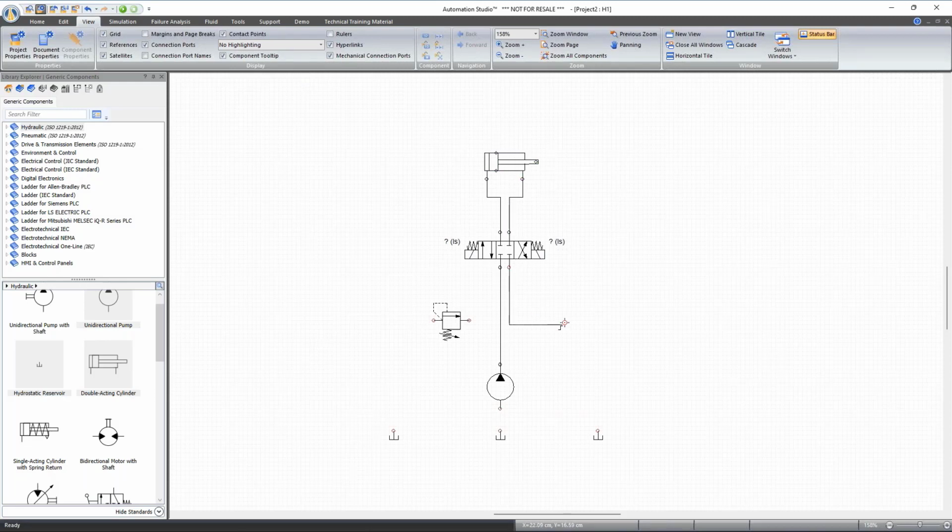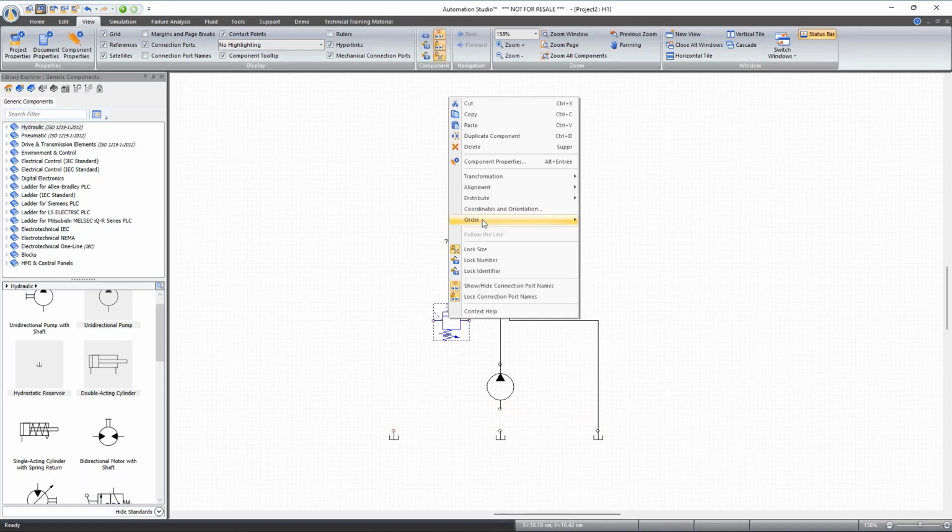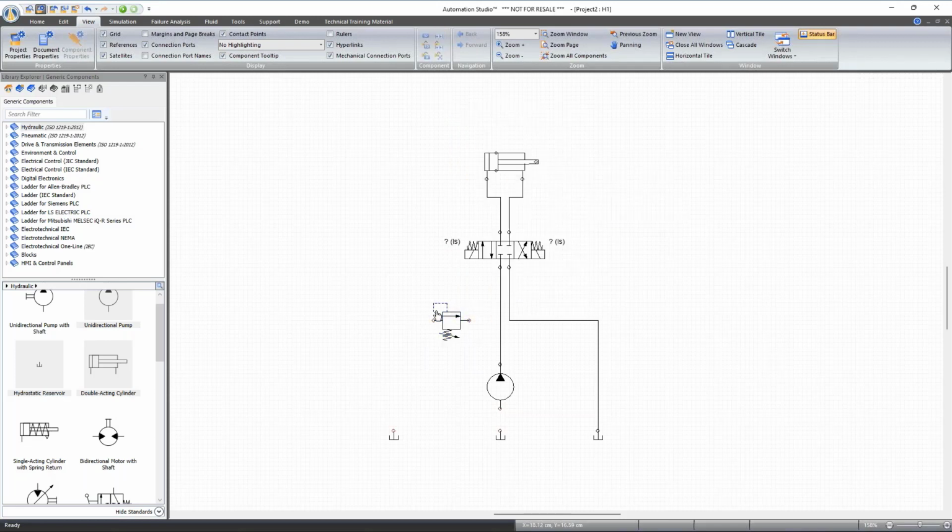Okay? So there are other keyboard shortcuts that can be defined. Let's say you want to flip this component. Of course, you can right click and do some transformation, rotate or flip. You can use Control R as listed here. You can define your own shortcuts. Me, I like this shortcut. So Control R, using this component, will flip it.